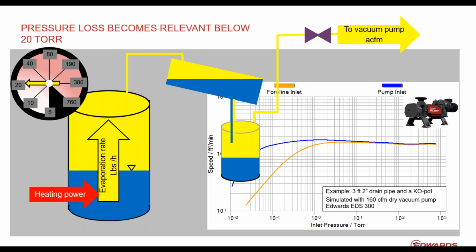What I frequently hear is, and it's true, it's a density related thing. So mostly we think in gas density and gas friction when we talk about pressure losses. It's gas velocity and density. So the first thought that derives from that is, well, if the gas density is going low, like in a vacuum system, your pressure loss is fine. It's getting lower. That's true until you hit a point where the same idea of going to a low density kicks in with another effect that I wanted to just briefly illustrate to you.